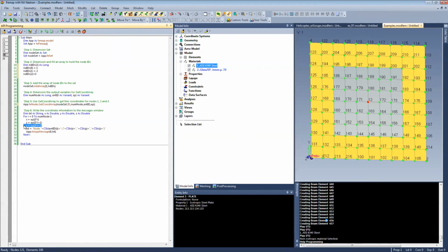And then I do some kind of fancy math here to get out the X, Y, and Z, because they're all in that same table, all squished together. But if you wrote it out, you would see that if you get 3 times our number of nodes, you would get the X position. Add 1 to that, you'll get the Y position. Add 2, you'll get the Z position, and then reset, and you'll get the next node. So that's how that works.